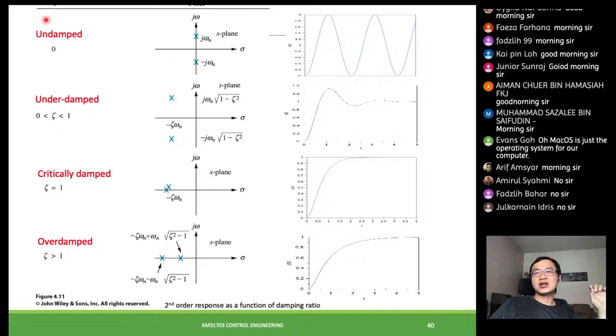This is an example of how you can find the damping ratio and the natural frequency. We know that once this is equal, we can get the natural frequency, which equals 6, and then we know this part will be 2 damping ratio multiplied by natural frequency. With the natural frequency of 6, you will get the damping ratio as 0.35.